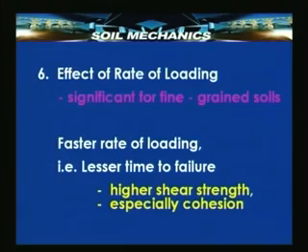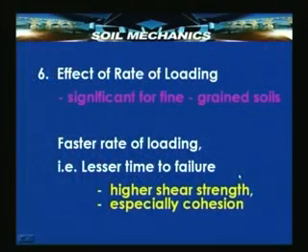If the loading is rapid compared to the rate of dissipation of pore pressure, then it is an undrained condition. So, fast rate of loading, less time to failure indicates undrained conditions, and therefore it gives a relatively higher shear strength corresponding to the total stress parameters, especially for a value of cohesion.